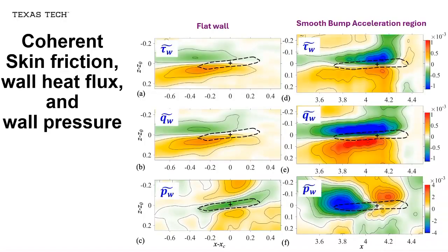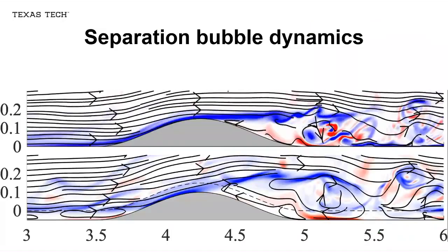This affects the momentum at the wall, but it does not affect the heat flux, because in the temperature transport equation, or the internal energy equation, pressure has no role in the transport of internal energy or temperature.